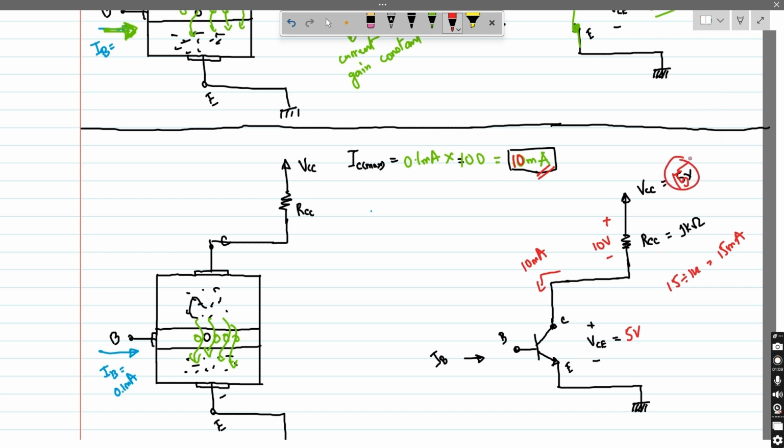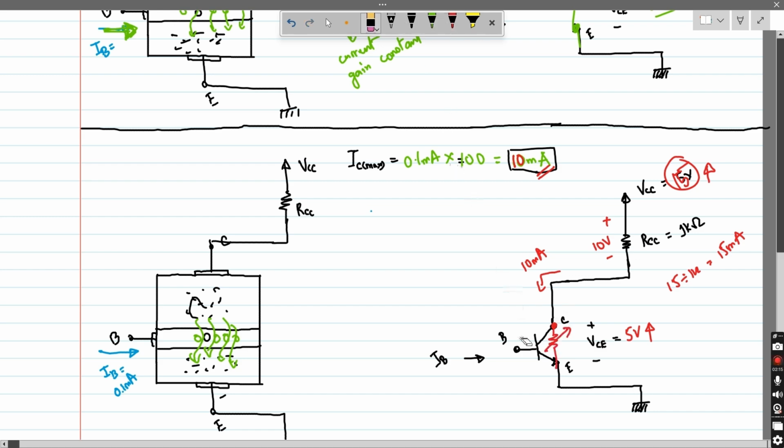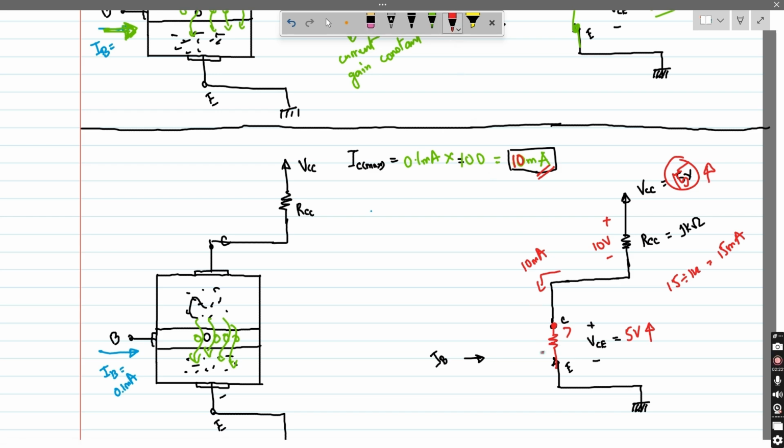If we increase the supply voltage further, the current will slightly increase, but the voltage drop across the BJT will keep on increasing. You can consider the BJT as a variable resistor whose resistance increases to ensure the current across the BJT stays according to the maximum current capability.